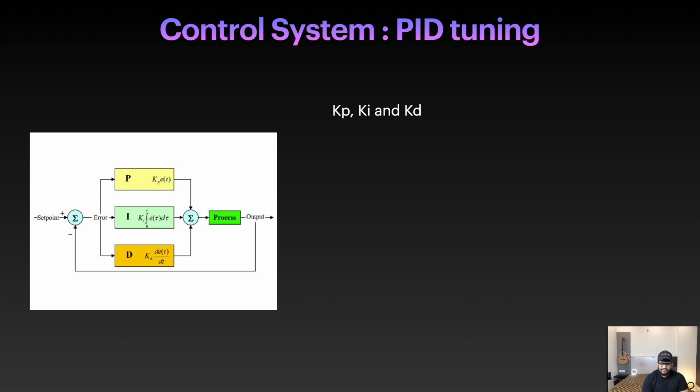If you talk about drone, what people used to do, every firmware comes with some default value of KP, KI and KD for each axis. So if you are using Betaflight, which I'm using, it's already pre-programmed into the firmware with some good to use, good to start values. But that is not for every system, because every system is different. Everyone is using different motors, everyone is using different propellers. Maybe you are running the same firmware in a bigger drone, and someone else is running it in a smaller drone. Maybe someone has a hexacopter, you have an octacopter, or you have a quadcopter.